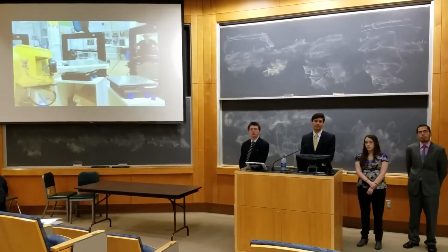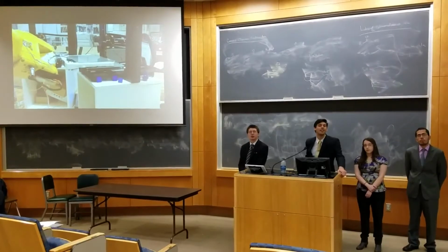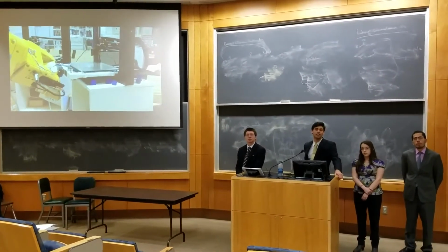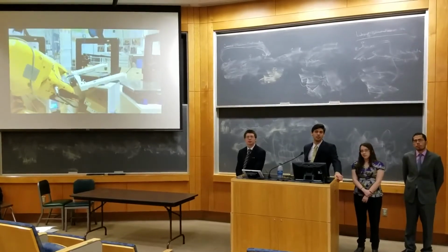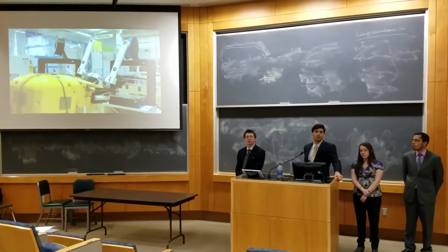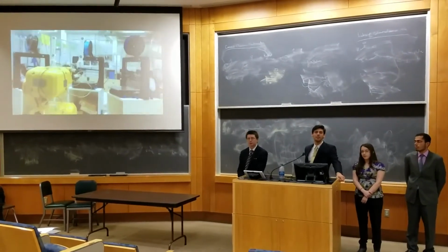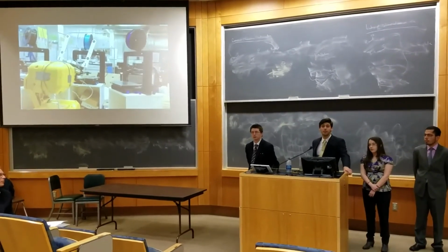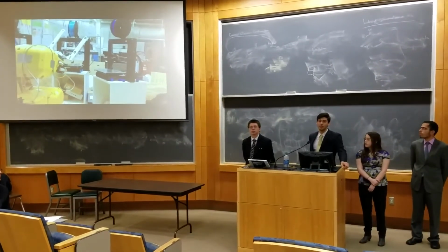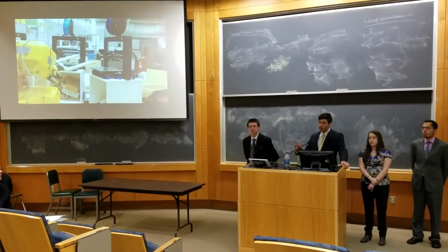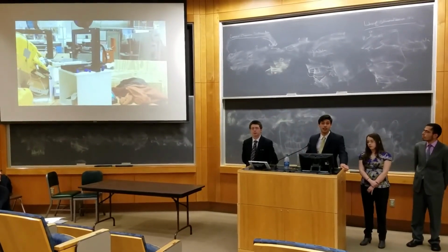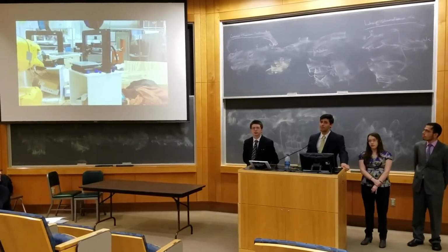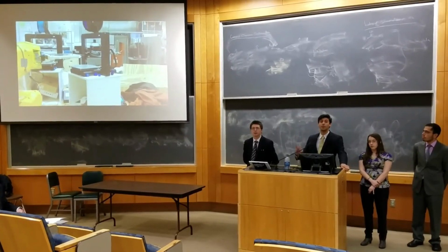So in theory, could you continue the system with another arm that would remove the print bed and the object, and then put the print bed back to a location where this arm could get it and reset it back on the printer? As one full cyclical system? Yeah, certainly. Especially with vision controls and OpenCV, you could absolutely design a system that can recognize, because of these printed parts, especially the more vibrant colors, stand out against the print surface. So you could absolutely design a system that can recognize the printed part and pull it off after it moves in.